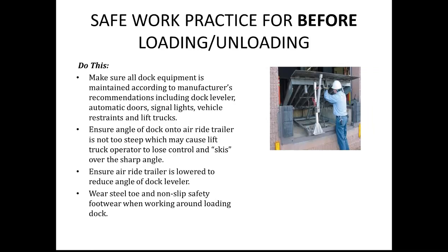That's what they call a pinch point. You want to make sure that your dock plates have that. Not all of them do. Because if one of your operators ever gets his foot caught between the descending dock plate and the edge, he'll quite likely either lose his toes or certainly he'll fracture his foot. So for that reason, safety footwear is absolutely mandatory on a loading dock.